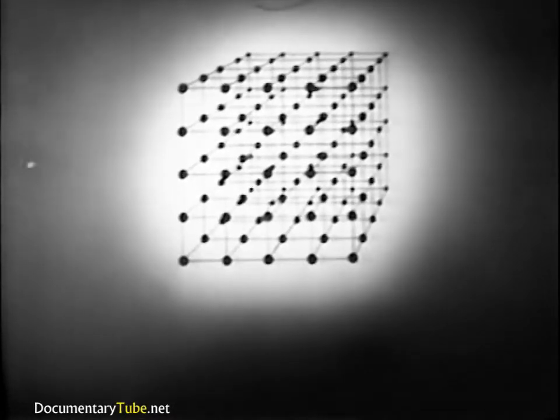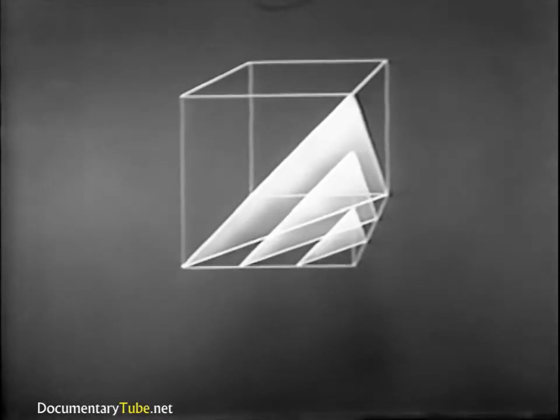These unit cells combine to form what is known as a space lattice. Within the space lattice, metal atoms exist in families of parallel planes with definite spacings between the planes. It is along these planes of weakness, called slip planes, that the crystal is most likely to glide or slip when deformed. These are important slip planes, along which movement may take place in the aluminum crystal. Through such movement, a crystal may undergo two types of deformation.